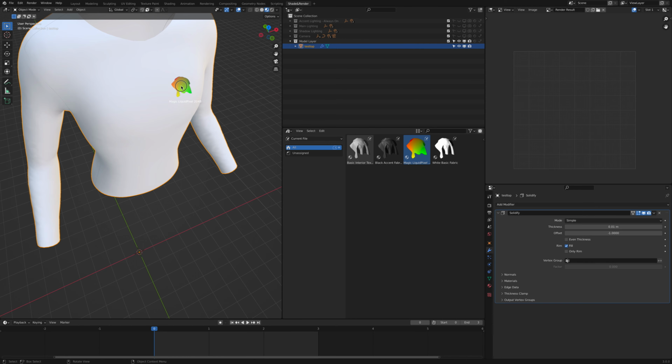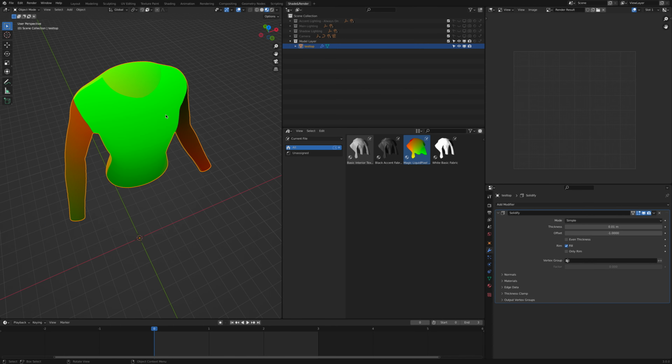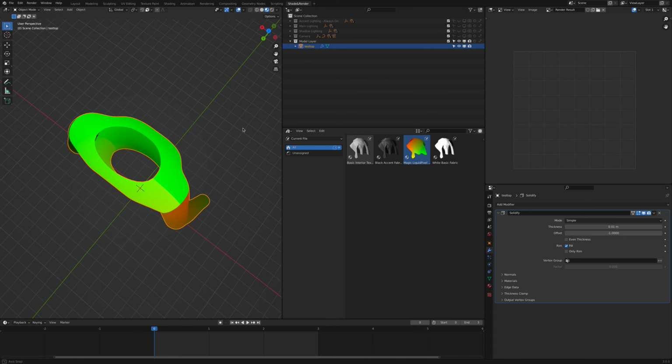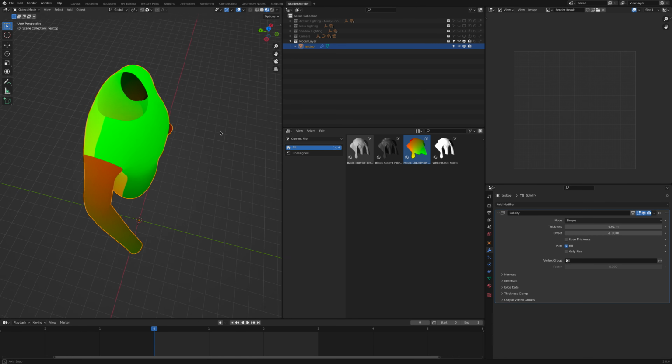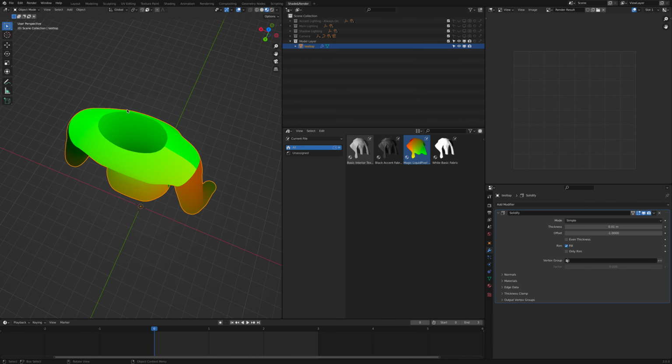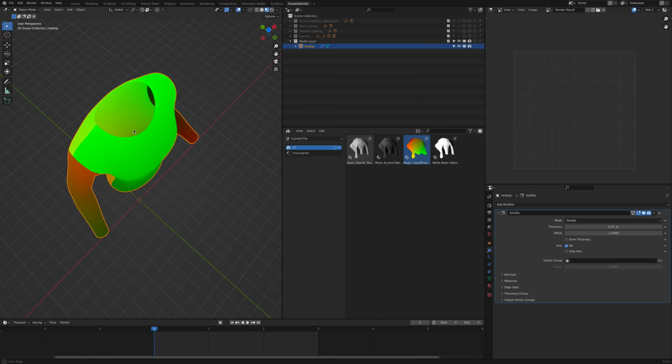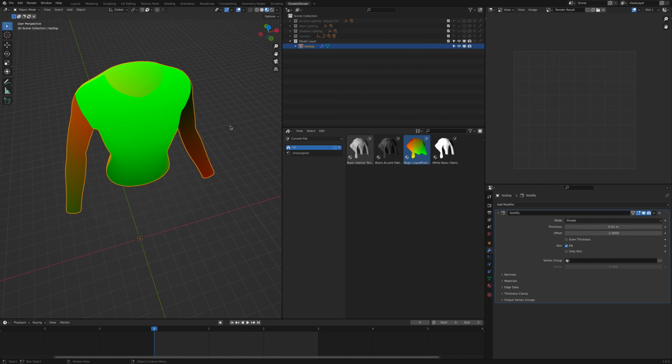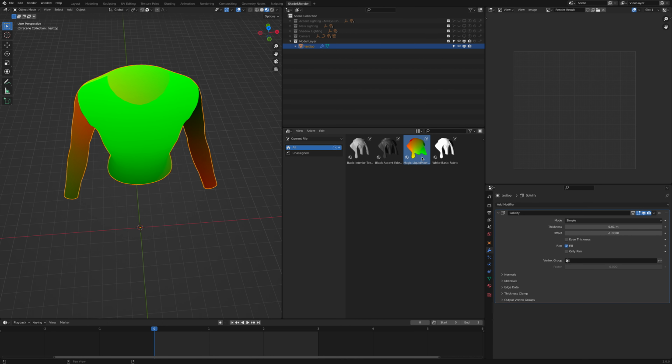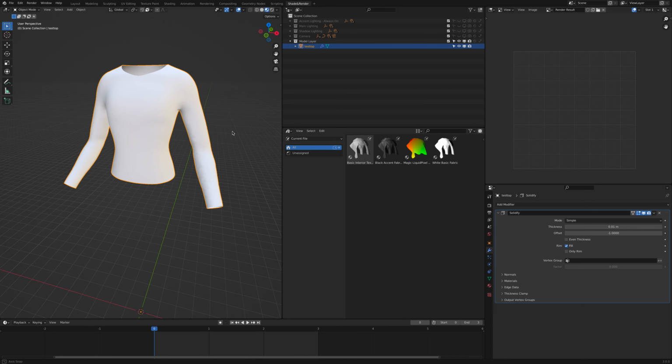So when we go to apply our liquid pixel texture, it's repeating the outside on the inside, which is bad, because when we go to set up our sublimation patterns on the outside, it's also going to repeat the sublimation pattern on the inside. So you don't want to see that pattern on the inside of the final garment. So we're going to undo that liquid pixel texture real quick.